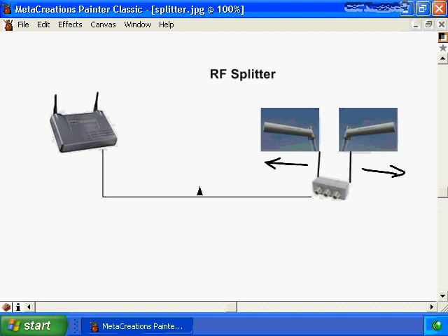And we also want to ensure that the cable lengths that are going from the outputs of the splitter to the different antennas here are of equal length, so we don't introduce more loss, because number one, we're splitting the single RF signal now into 2 different independent signals, and the longer the length of the cable, the more attenuation that we have. So we want to ensure that the length of the cable that is being split off in these 2 independent RF channels is of equal length. So we reduce the amount of attenuation by adding in these new cables.